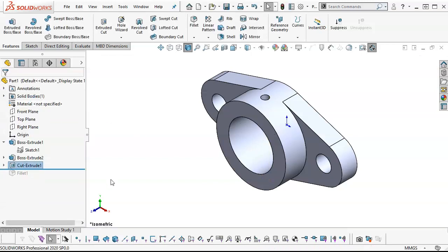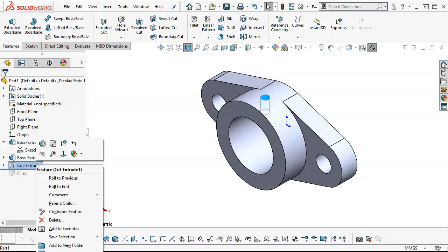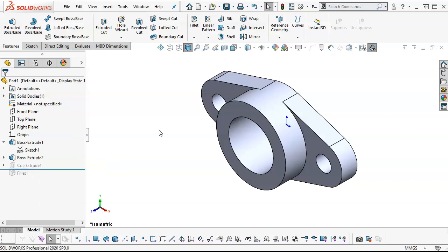terminate. Alright, so one of the things I did automatically without even thinking about it was the rollback bar. And so when you see the little fingers on the bar, I rolled it back in above the fillet, and that creates kind of a suppression state that anything I insert will be above that bar. If I want to go with another method, then I can suppress.